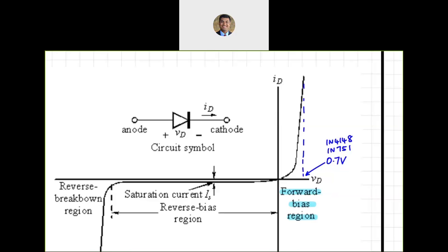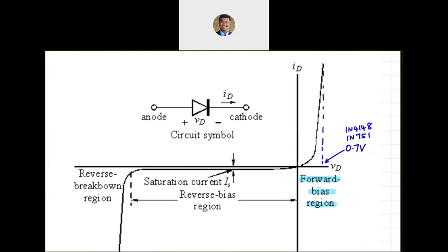Notice over here, the voltage across the diode can never be 1.2 volts or 1.5 volts across one diode, as we are seeing over here. It is going to be between 0 and 0.7. Maybe experimentally we may be able to get about 0.75, for example, just a little bit more, but not too far ahead. So just keep that in mind, so that when we get to the experiments, we can relate this to the IV characteristics.